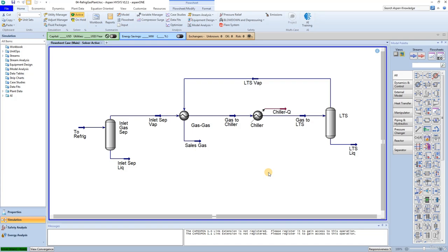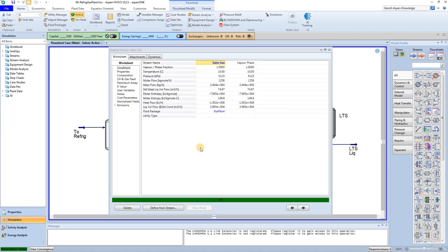If you open the property view of the cell's gas stream, you will notice that the three parameters are all calculated. So there is no direct way to calculate the dew point temperature at a different pressure value. Adding a component mole flow balance allows you to create a second stream with the same flow rate and composition as the cell's gas without fixing the vapor fraction, temperature, or pressure.